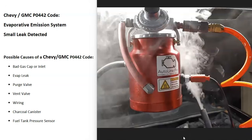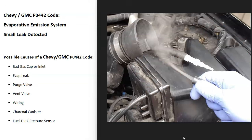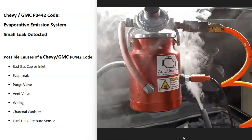If you took it to a mechanic, very likely what they do is they feed smoke into the evap system, and then wherever the smoke comes out, they would know where the leak's at. This is very common. There's some low-cost smoke machines on like Amazon or eBay. I'll put a link down below if you need one. There's also YouTube videos on how you can make these up for like $5, $10. But using a smoke machine and just checking to see if there's any leaks, any hoses or anything like this is a good troubleshooting method that many people use.